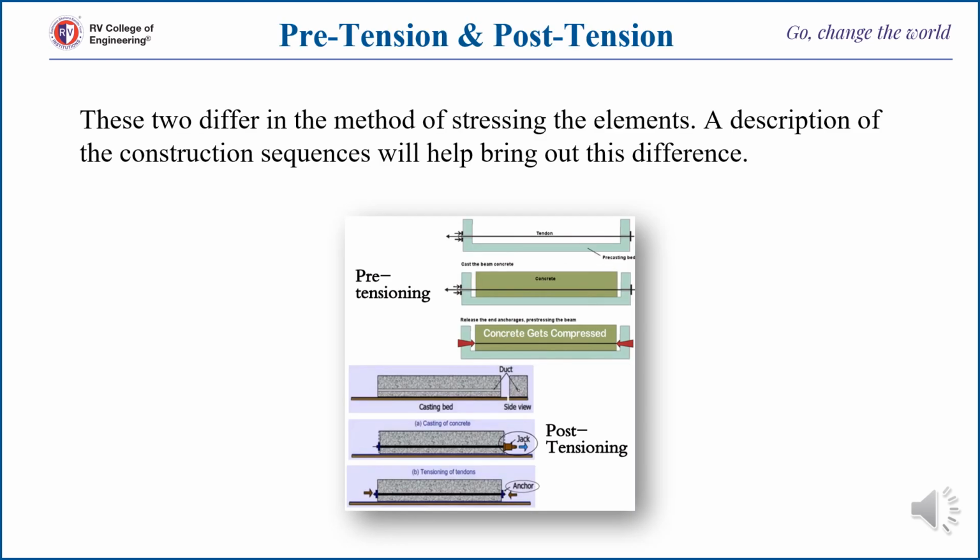Pre-tension and post-tension. These two differ in the method of stressing the elements. A description of the construction sequences will help bring out this difference. In the below image, we can see the pre-tensioning and post-tensioning process of the pre-stressed concrete.